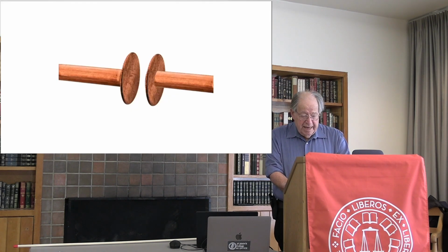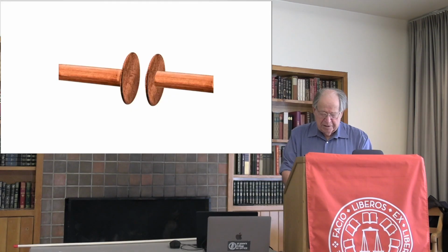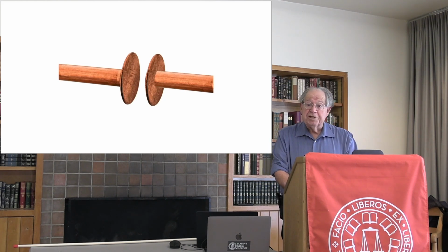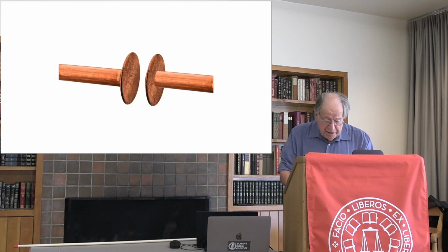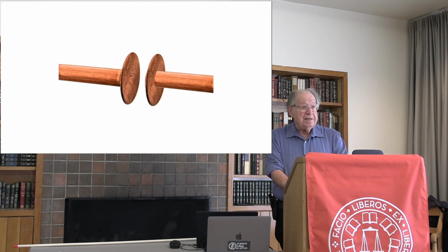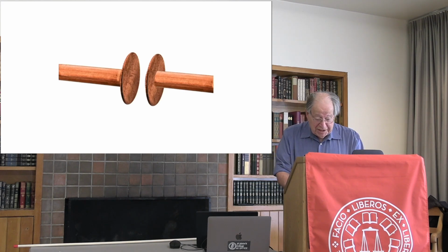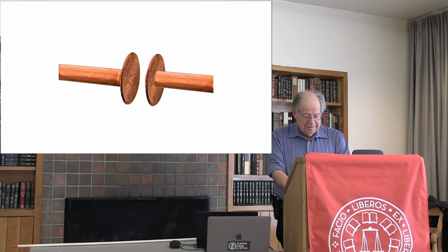But this view reflects only the limited standpoint of steady current. For if you were to flatten out the exposed faces of the cut wire, making them larger and larger, again, a mere change of shape, you would form a set of parallel conductive surfaces, a capacitor. Thus, every severed wire is, in effect, a capacitor.